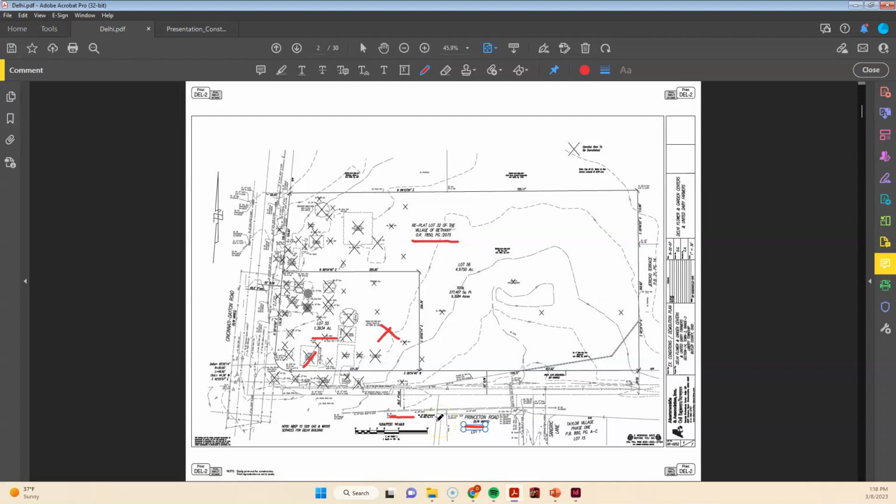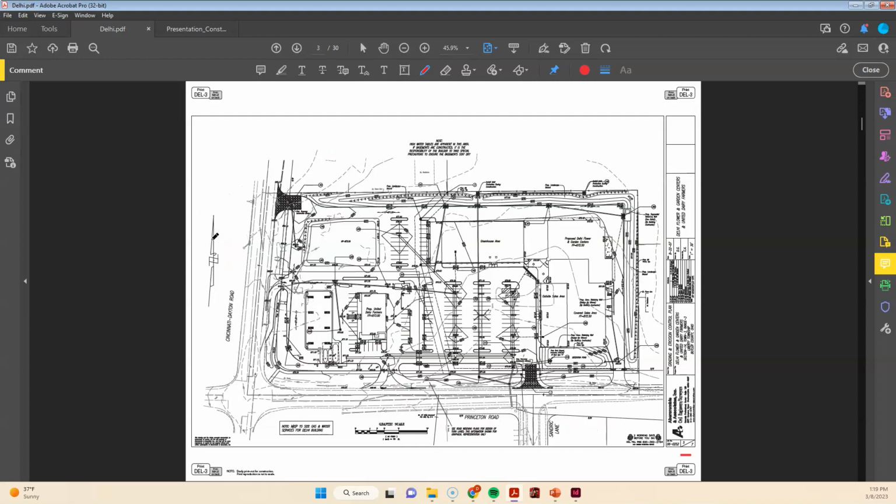But a multi-purpose drawing. This is what I was going to talk about, though, with the architecturals. That is the north arrow. Very important. That is telling us that I would assume solar north is up, and therefore east is over here, west is over here, and south is down here. That's how I would read that, as a solar north arrow, different from a project north, and I'll talk about that in a minute. Let me go on.